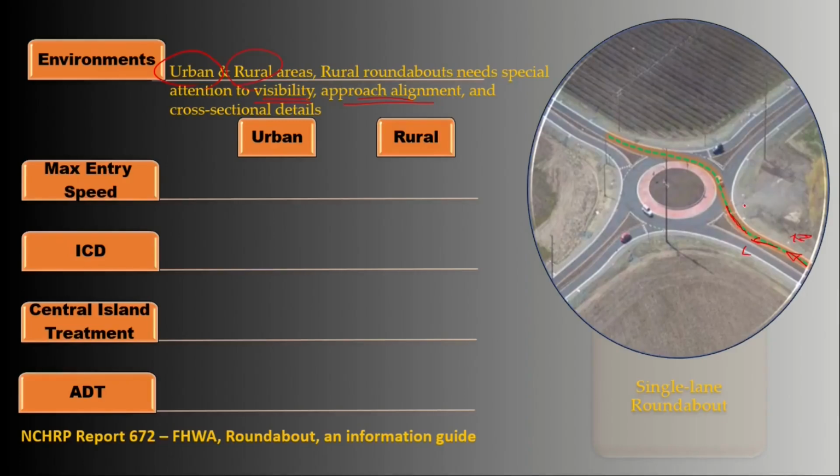It's a matter of the second section, but the general idea of this alignment is to slow down approaching traffic step by step, normally 8 miles per hour in each step, so it reaches the roundabout at a speed of below 30 miles per hour. Otherwise, the driver could lose control of the vehicle and end up rolling over, running off the circulatory roadway, or colliding with the central island.